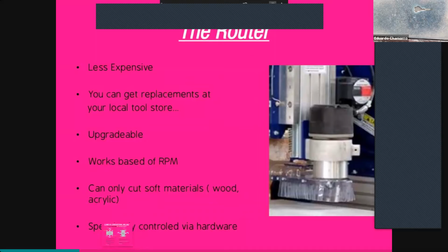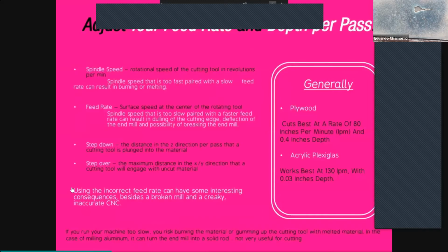When you were saying that if we go with a faster speed, we need to secure the material better, is it only the screwing outside the material, or also, for example, when we are creating a circle with larger parts, so the circle doesn't fly away? If you don't fix the material, it does this, literally, but at really high speed. So you need to fix everything.